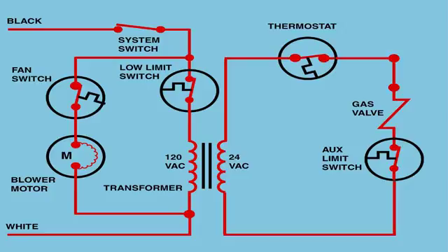Normally, the blower cycles on the fan switch and the burner cycles on the thermostat. When the living space reaches this thermostat setting, the thermostat opens, which causes the gas valve to close, which shuts down the burner. Eventually the plenum cools, which opens the fan switch and shuts off the blower. The system then sits in standby until the thermostat cools down again, starting the cycle over from the start.